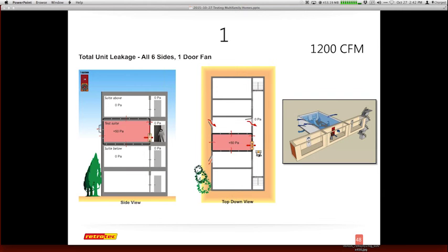So he's asking about creating a pressure relief. So should I try to get the units next to me if I'm going to do a single fan like I'm doing right now? I would actually follow what the guidelines are, because whenever I'm dealing with a code or similar situations, I would want to find out what I am allowed to do to the adjoining structures. If you open up the adjoining structures, it could make your unit appear leakier because I now have an area for that pressure to go to.